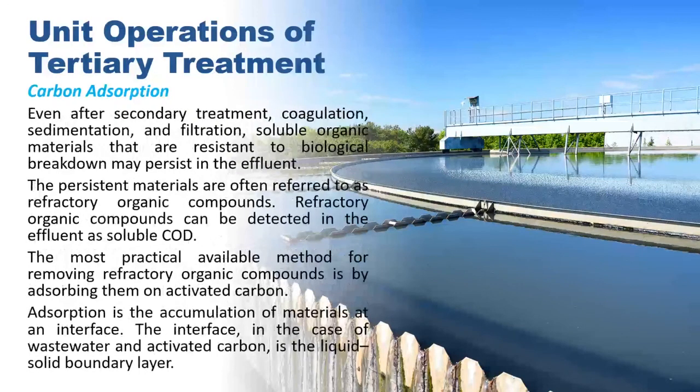Now let's move on to the carbon adsorption, which is one of the unit operations in tertiary treatment. Even after secondary treatment, coagulation, sedimentation, and filtration, soluble organic materials that are resistant to biological breakdown may persist in the effluent. The persistent materials are often referred to as the refractory organic compounds. Refractory organic compounds can be detected in the effluent as soluble chemical oxygen demand. The most practical available method for removing refractory organic compounds is by adsorbing them on activated carbon.